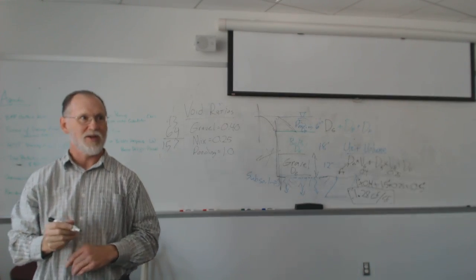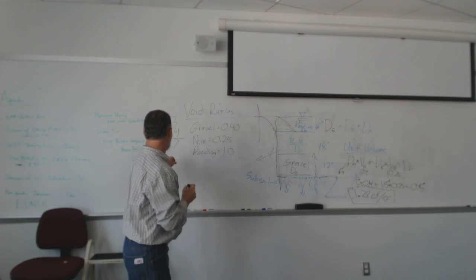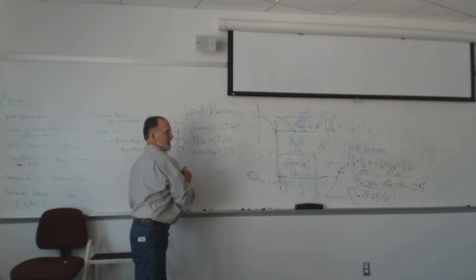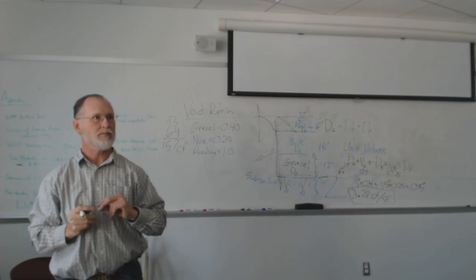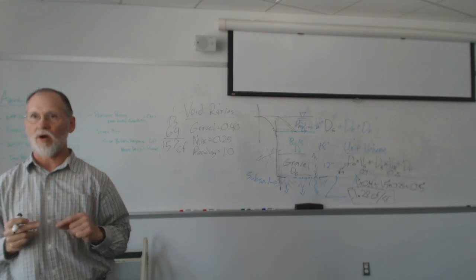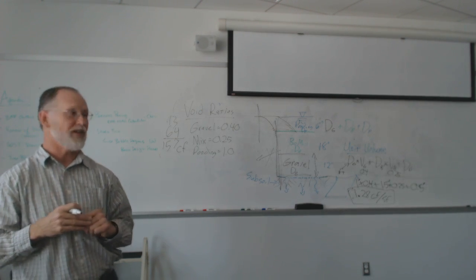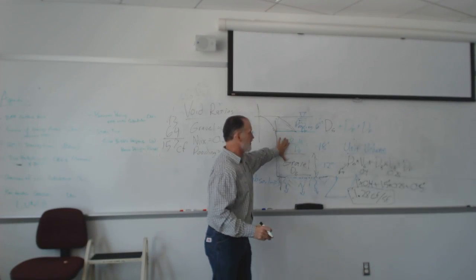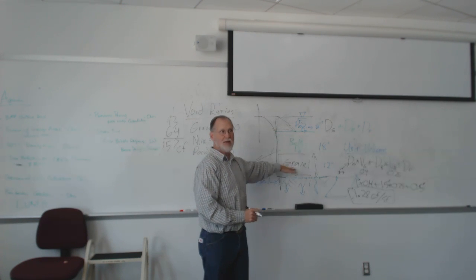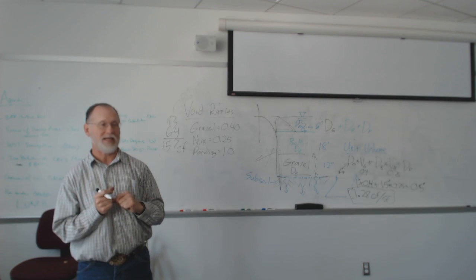Does that sound right? We're going to find out how badly I sized that rain garden. So 157 cubic feet is for my 1-inch storm. We determined how much runoff we got to the area where we're putting our rain garden. Now we want to see, for this specific design of aggregate, biomix and ponding, how many square feet that would need to be.